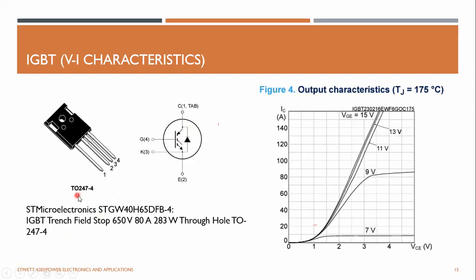Right. So this is taken from a data sheet. This is the symbol of an IGBT. Sometimes there are 4 pins in IGBTs, not like 3-pin devices. An additional emitter is provided as number 3 for gate driving purposes. So when you provide 7 volts or any voltage lower than 7 volts, the device is turned off. When you provide any voltage over that, the device is turned on.